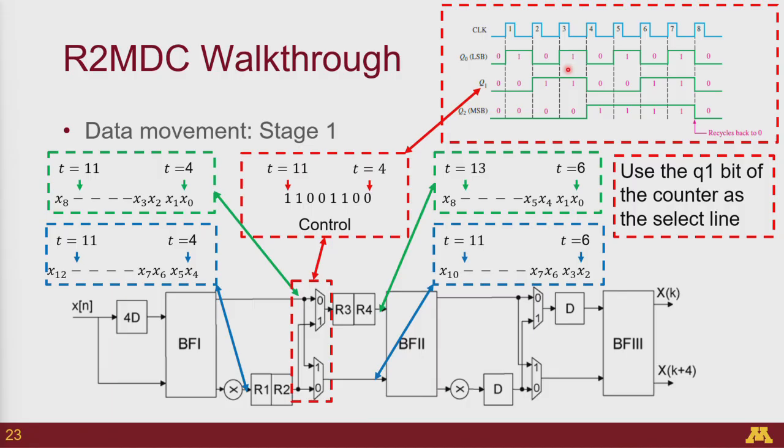It depends if you implement it as a single port ROM versus a dual port ROM. A single port ROM can only read one value at a time. A dual port ROM can read two values at a time. So generally, the number of lookup tables would be the number of multipliers divided by the number of ports each ROM has.